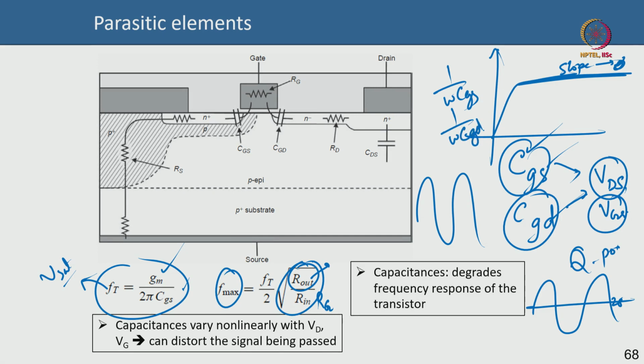That is a headache, because of the matching of the amplifier. When I say match, we mean the impedance looking into the load, conjugately matched to the output impedance of the device. The impedance matching happens for a specific frequency. When your capacitances keep changing with every cycle of the RF, your matching conditions can change, and that is a headache. So, nonlinear modeling is very important.